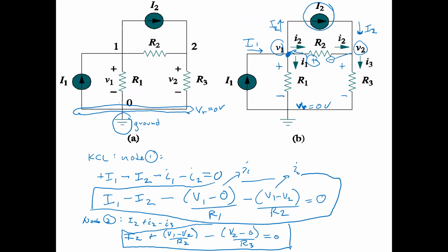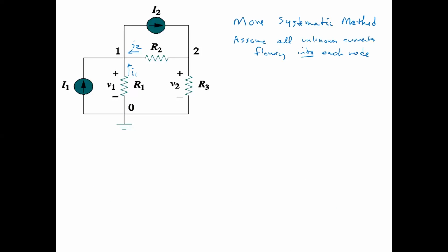It's a small change, right? We're just changing the understanding of how the currents are flowing into or out of those nodes, so that we're going to define those currents at each node as if all the currents through the resistors are flowing into the node, and we're just going to define the element voltages with that reference direction and add them up really fast. And this becomes very mechanical and systematic when you do it this way. Let me explain how that works.